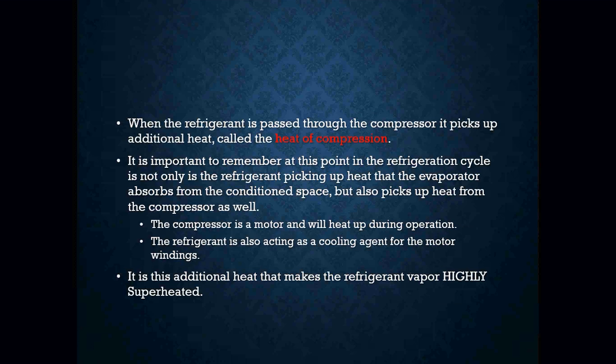We're using the refrigerant to act as a cooling agent to keep those motor windings cool. So as the refrigerant passes through the compressor, it is picking up even more heat. So that line is going to get extremely hot.